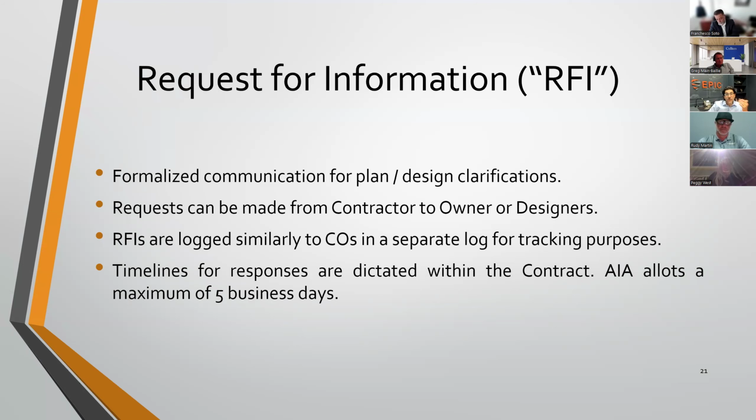And during the throes of actual construction, it could be a question from the contractor to the designer or the owner, but to the designer, saying, okay, architectural plans show the floor elevation at X and the structural plans show the floor elevation at Y. Which one do you want me to build to? And by the way, my expectation was you wanted X. So if it is Y, expect a change order. Or here's the change order that corresponds to that if that is your answer. That is going to happen through the RFI realm. These are just documented questions during the course of construction.